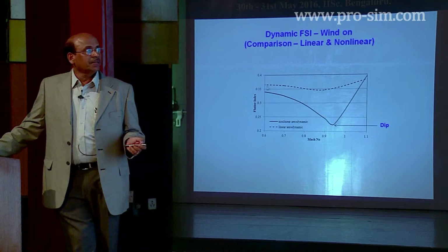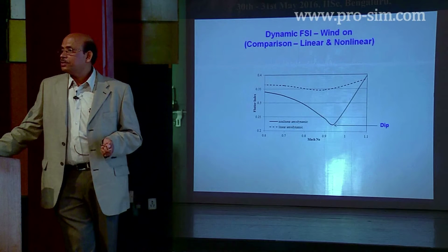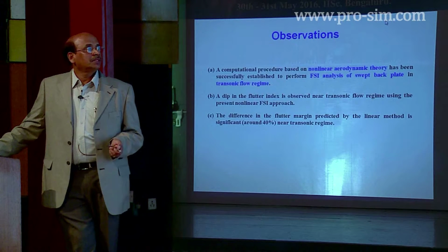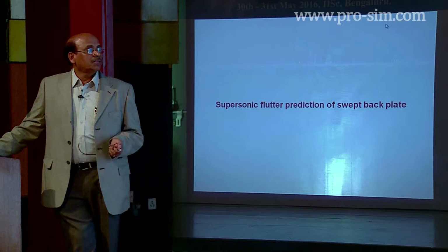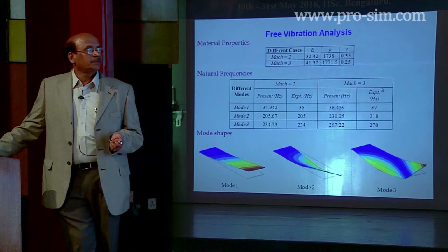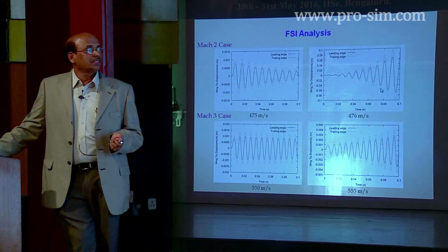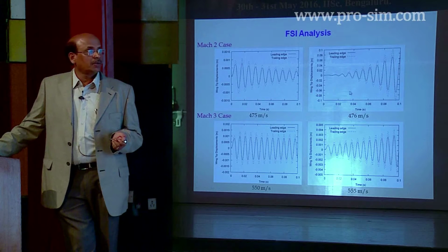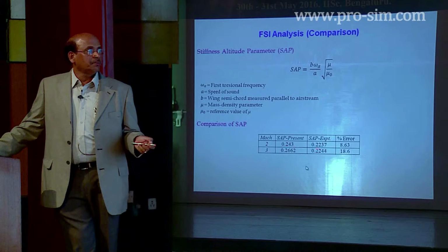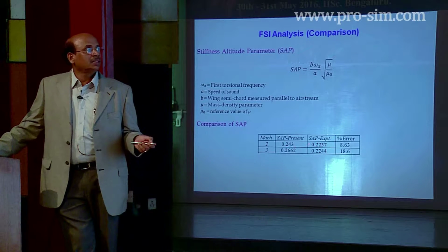So it is this particular phenomenon which we are able to successfully capture using the fluid structure interaction analysis. Okay, I already told the observations. Similarly, we have done the supersonic flutter prediction for the same swept-back plate. This is the finite element model, natural frequency and so on. This is the time history and other things that are plotted. And we have computed using the present method and compared with those obtained through the experiments.